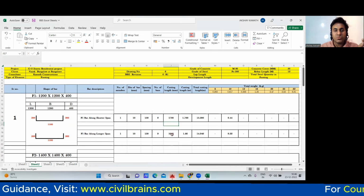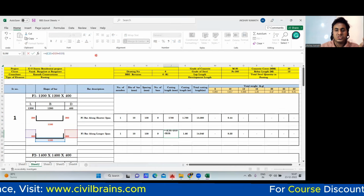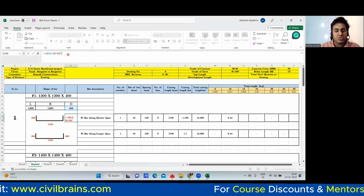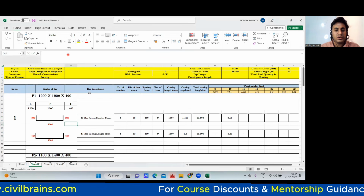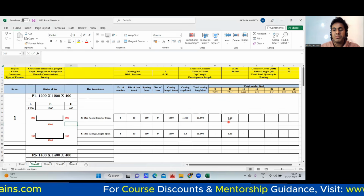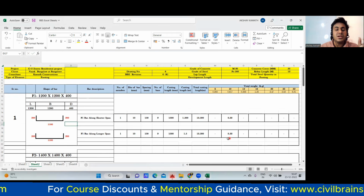So criteria number one is satisfied, right? Finish. Second, you apply 2/3 of the depth. So 2 by 3, if you do, it will be 200. Accordingly, you see your cutting length will be this time 13.5 and 8.33. Previously, it was something like 9, so hardly there is any difference now.